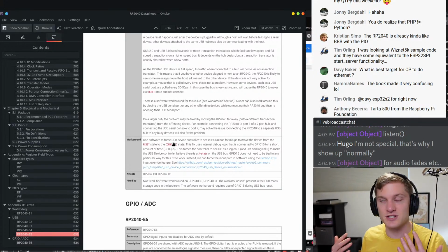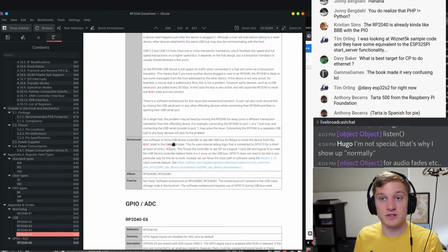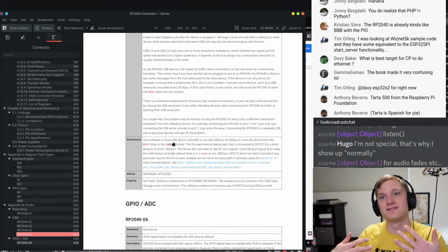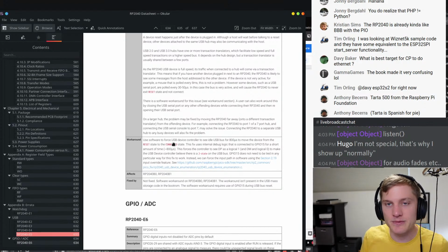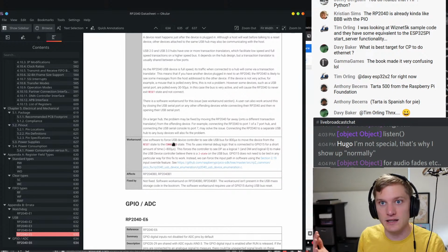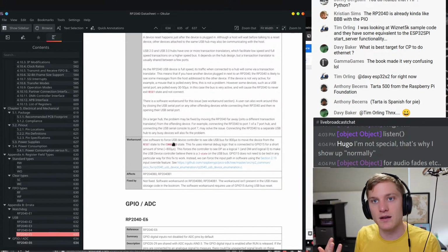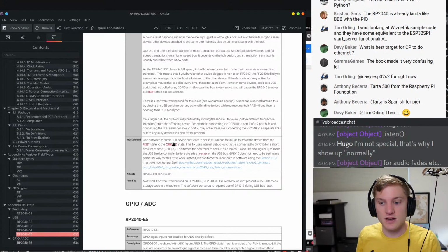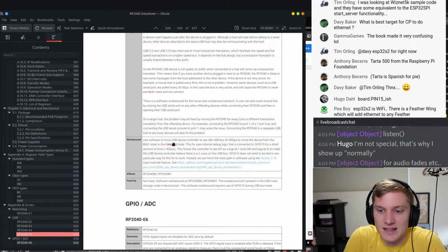And there's this chance that if you need to reset your USB bus, it will take over the pin and not quite put it back to its own state. CircuitPython is probably not a big deal because CircuitPython, when you connect to USB, will likely rerun your code, and when it reruns your code, it will reset the state of that pin, and then it'll work again. So it's not super fatal, but yeah, it's kind of a pain.